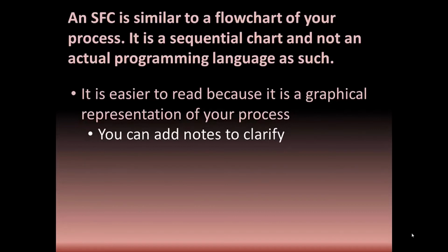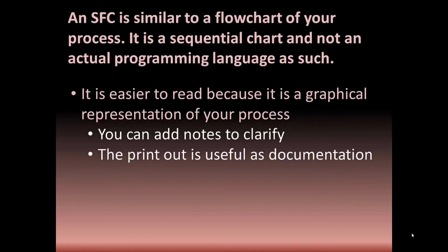With ladder logic diagrams, many of us do sit down and kind of do a graphical representation of the process, and then we sketch in what we want in each section, and then we sit down and we actually program and put flesh onto it. And the printout of the SFC, the sequential function chart, is a very useful part of your documentation.